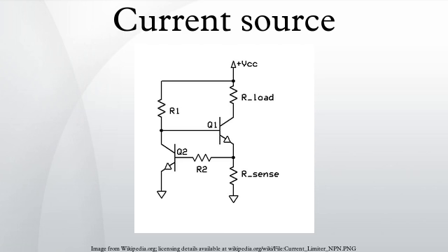Keristor tubes, nitrogen-filled glass tubes with 2 electrodes and a calibrated Becquerel amount of 226Ra, offer a constant number of charge carriers per second for conduction, which determines the maximum current the tube can pass over a voltage range from 25 to 500 V.